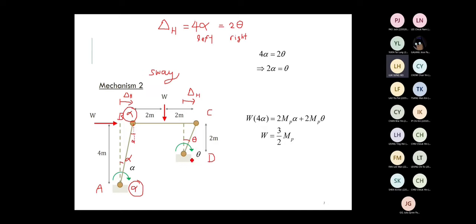Okay, I circle the total rotation at different plastic hinges. Point D, I go to point D first. I think point D is easier. Point D is at the ground level. The rotation at point D is equal to theta. I think this one is pretty straightforward. Point C, finally. The idea of point C is quite similar to point B. Point C is connecting 2 members, beam and column. The beam remains horizontal, no rotation, while the column is under rotation theta. So what is the total rotation at point C? The total plastic rotation is equal to theta, right? Only one side. So what is the total rotation in the whole structure? Alpha plus alpha plus theta plus theta, right? 2 alpha plus 2 theta.